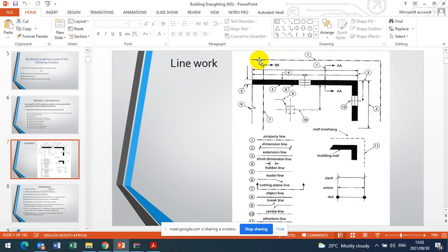But that boundary line layer is red color. If you leave it under red, it's going to be a thin dashed line. We need it to be a thick dashed line. So the color should be green. You need to change the color property to green, but under the layer boundary line layer. Did I make a point?